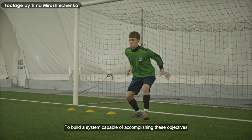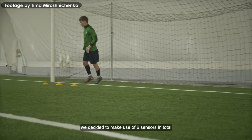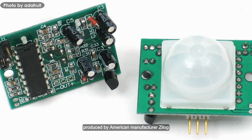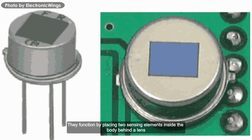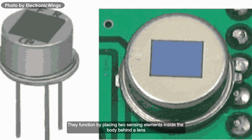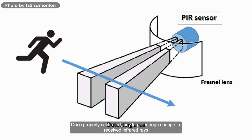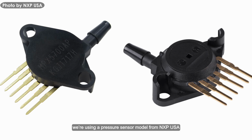To build a system capable of accomplishing these objectives, we decided to make use of 6 sensors in total. 2 of them would be the passive infrared motion sensor, produced by American manufacturer Zilog. They function by placing 2 sensing elements inside the body behind a lens, waiting to receive infrared radiation from the outside. Once properly calibrated, any large enough change in received infrared rays would result in a change in its output voltage. As for the remaining 4 sensors, we're using the pressure sensor model from NXP USA.